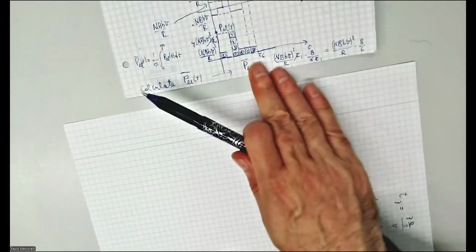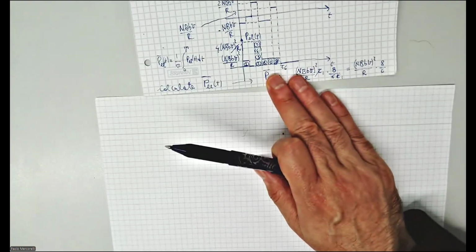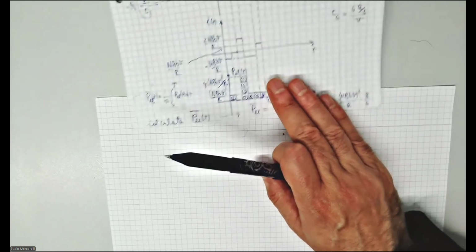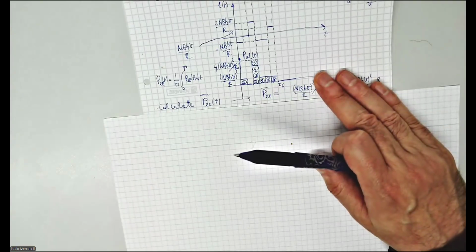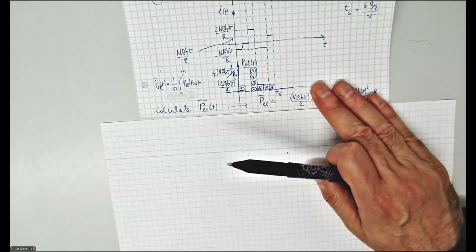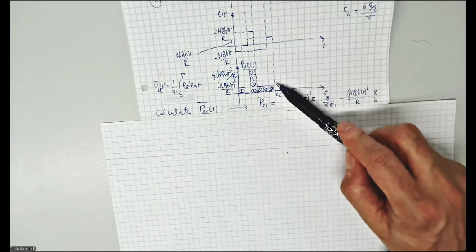Now power. Also easy, no? You don't have to look at the data sheet. U induced squared divided by R. Basically, it is always positive in this context. This means, in accordance with the convention, it is the power which I dissipate on the resistance, because it's positive, which equals minus the power which I generate with the U induced. One is positive, one is negative, no? In the circuit you have 2 elements, you remember from electrotechnique.